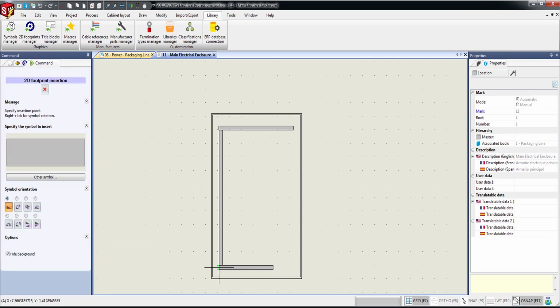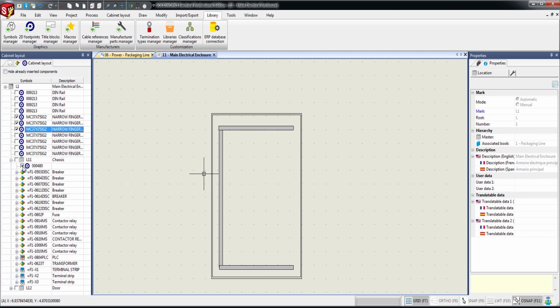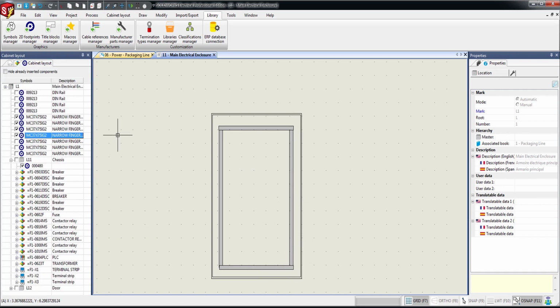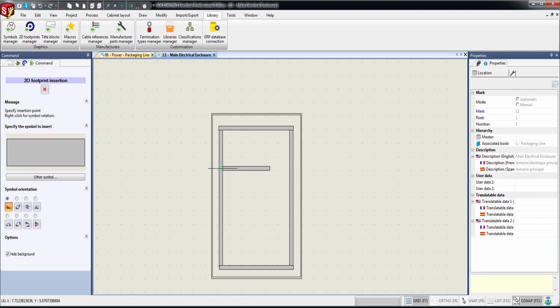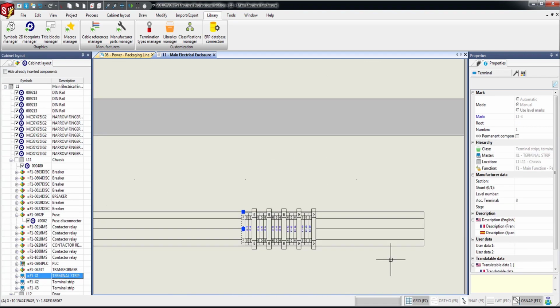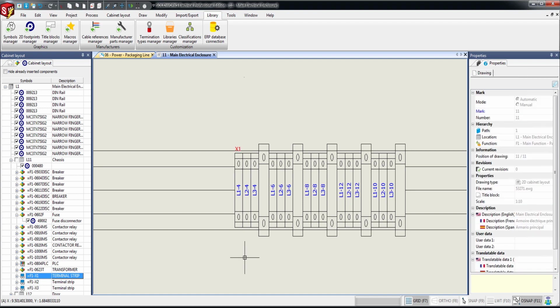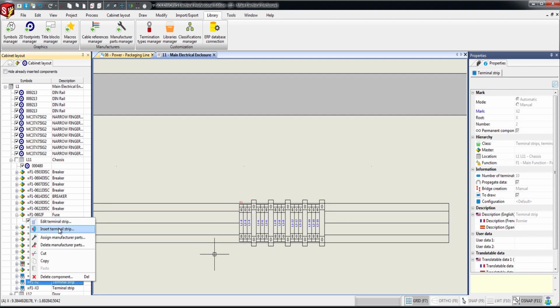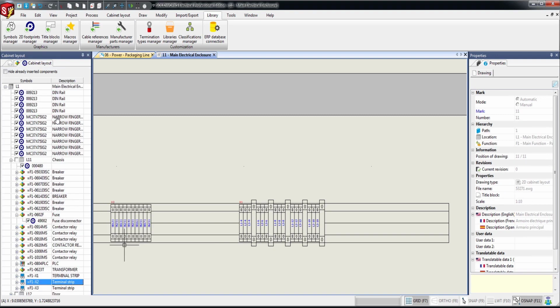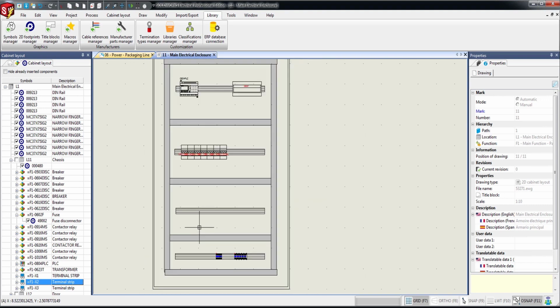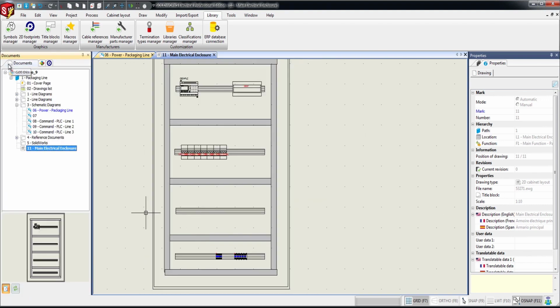But you've found that you're dealing with a lot of O-snaps and a lot of mouse clicking. Maybe those symbols that you are wanting to drop on your DIN rail aren't necessarily centered on your DIN rail, because then you have to do things like using O-snap and a center line. But you can get some great views of your drawings, including your terminal strips. But in a large size drawing, you may lose some of that detail when you zoom out or create that print.